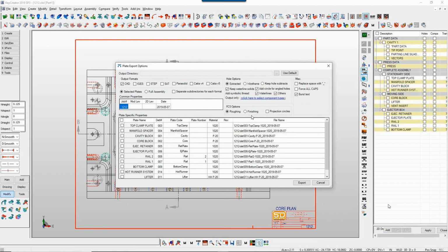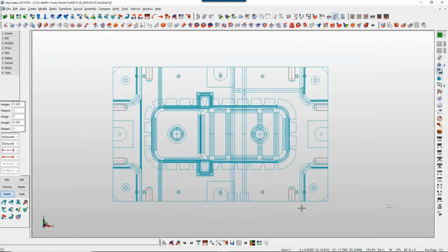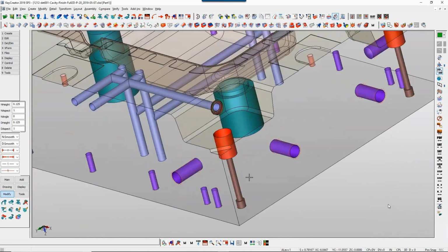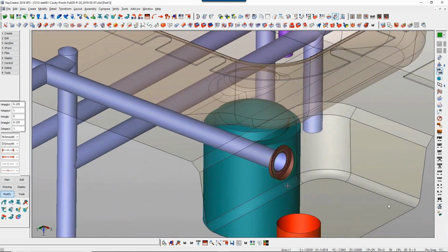So it just depends on the software that you're using. We also do another cool thing with angled add circle for angled holes. This is for our users out there that utilize certain technology, especially for gun drilling. The way the technology works is it looks for two circles, a starting circle and an end circle. And that's how it figures out its drilling procedures.